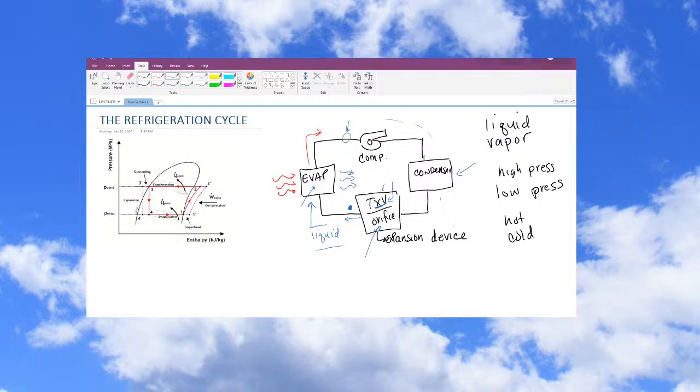So then that compressor starts to literally do its job, compress, right? Compress that vapor into a high enough pressure that it's going to want to become a liquid again. But the compressors, just like your turbocharger in your car or your air compressor at home, they add energy, they add heat to it. So the heat level leaving this compressor is actually really high. There's a lot of heat in here. And we've got to get rid of that heat if we want this to become a liquid.